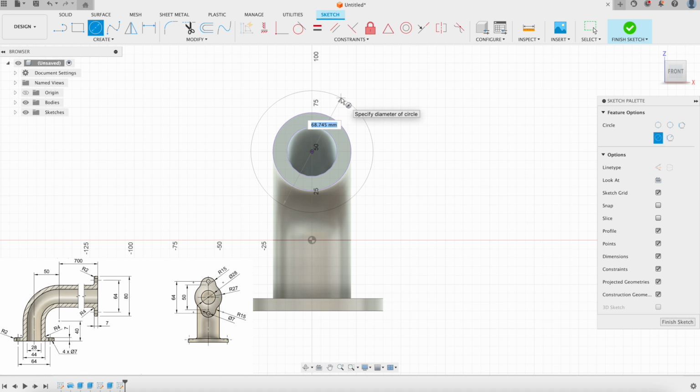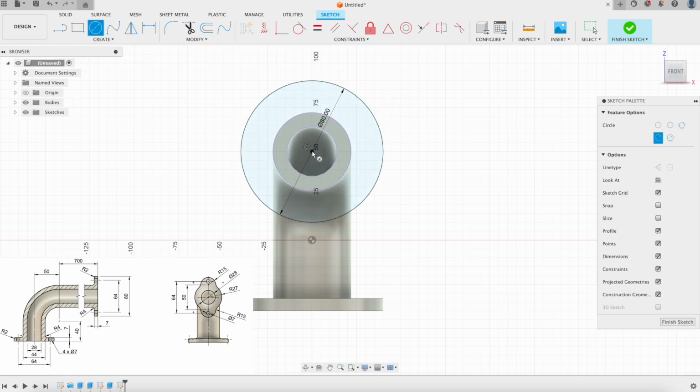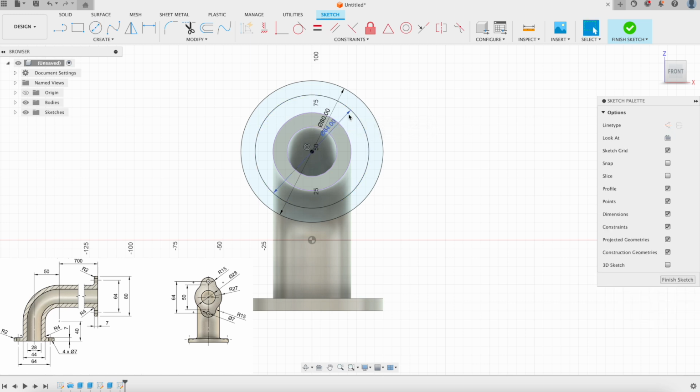If we look at the section view, we see that from the very top of this funky shape to the bottom, we still start with an 80 millimeter circle. We're just adding some intermediate steps along the way. Okay? So we still start with that 80 millimeter circle, and we also still have that 64 millimeter path where the smaller 7 millimeter circles fall in line. So we'll start with both of those same 2 things, same as before.